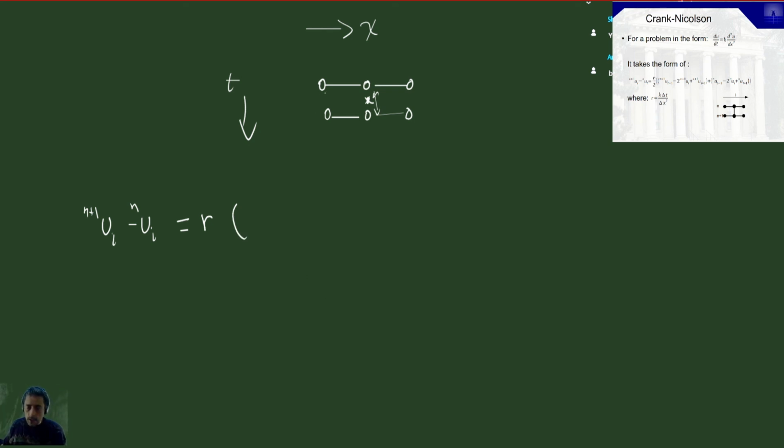So it's at time n plus 1, and this is at time n. So what's the average? Well, I have here my pressures at time n plus 1. So this is at i minus 1, i, and i plus 1. So I want my pore pressure at i minus 1, minus 2 ui. This is the same procedure we did the first time, so I'm not repeating.